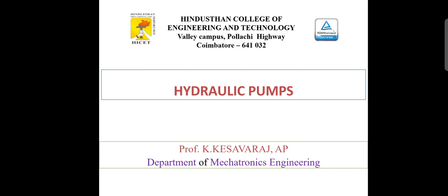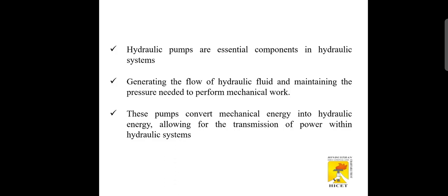Today I am going to present about hydraulic pumps. Hydraulic pumps are essential components in a hydraulic system. It generates the flow of hydraulic fluid and maintains the pressure needed to perform mechanical work. The hydraulic pump converts mechanical energy into hydraulic energy for transmitting power within the hydraulic system.